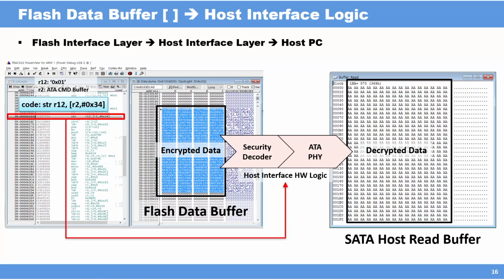you can see. Although we have no idea about the logic, in AES-XTS generally, the block encryption key is altered per LBA. To decrypt the ciphertext properly, we should already send the LBA corresponding to each ciphertext to the controller. Only then do we get a match.